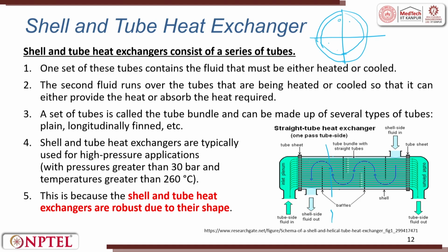Inside the shell, you will see several tubes. This is a front view, this is a side view, and you will see tubes. These tubes have to be held in position, and that is done by baffles. A baffle is again a plate which has several holes in it, so the pipes pass through the baffle. From here to here it passes and holds these pipes, then from here to here it holds them again. So, it holds the pipes in their regular position. So, this is held by baffles: shell, tube, baffle, right.